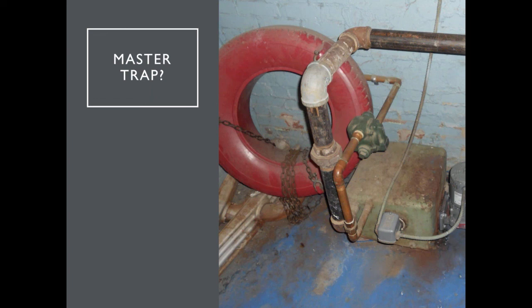Okay. And Dan is wondering, so should the goal for a system be 2 to 3 psi and all equipment/design choices be targeted to that? Yes. What we find though, a lot of times, on a commercial building with steam to water heat exchangers, you really need to find out what their pressure design is.